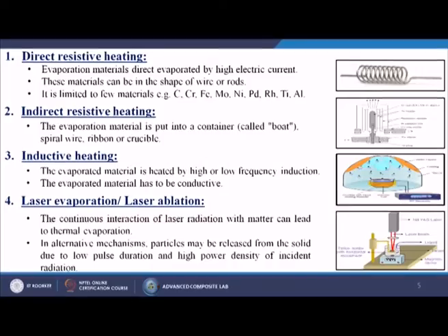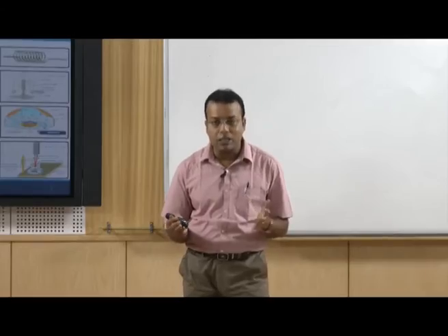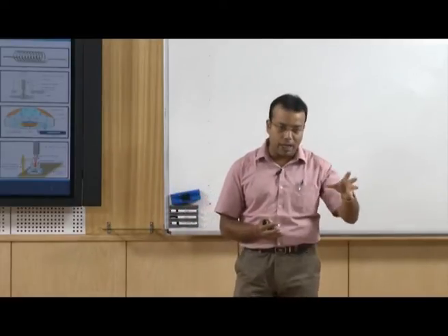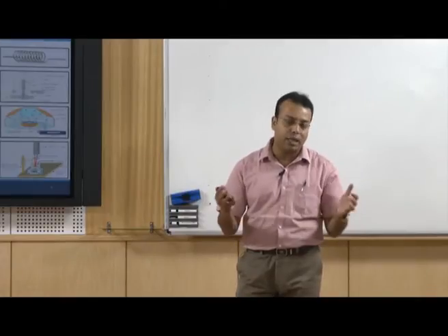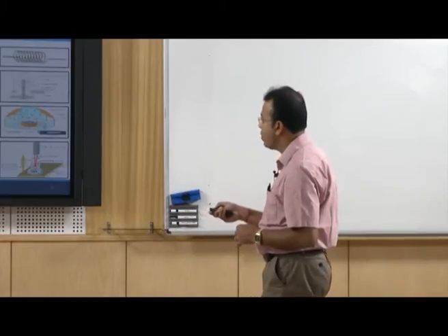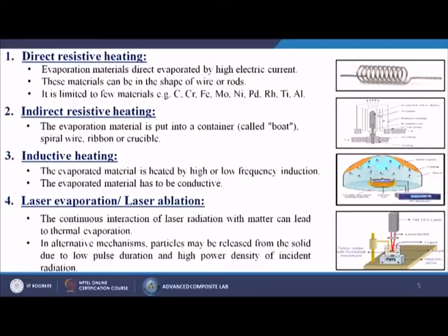Then laser evaporation, or laser ablation. From this particular figure we can understand that here the source of energy is the laser. We simply apply the laser onto the source material so that it can come into the vapor form, and then that vapor can be deposited onto your material surface. Continuous interaction of laser radiation with matter can lead to thermal evaporation. In alternative mechanisms, particles may be released from the solid due to the low pulse duration and high power density of the incident radiation.